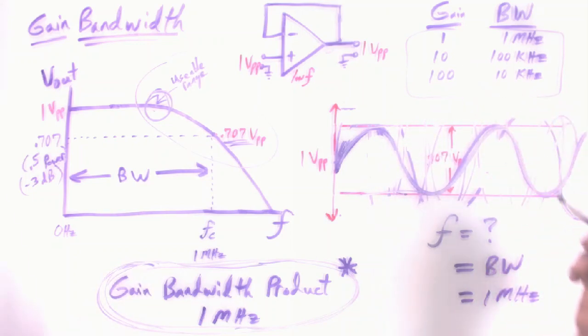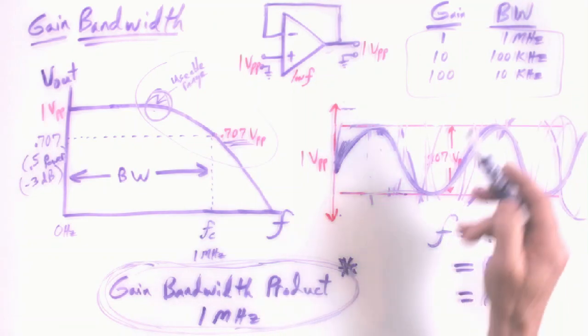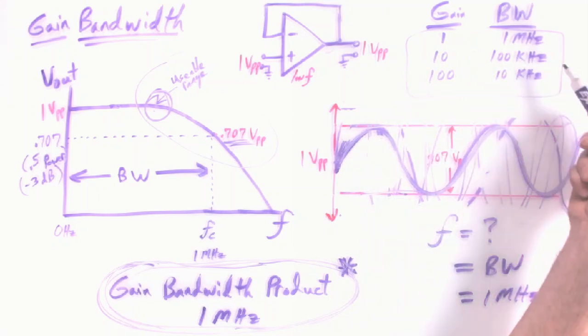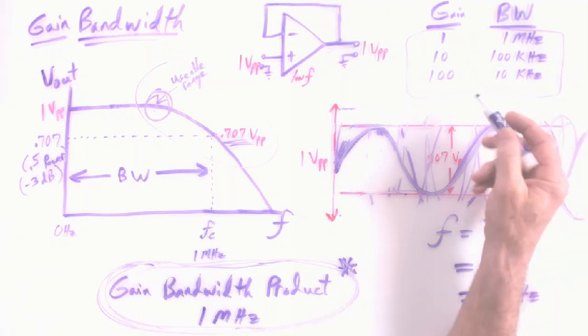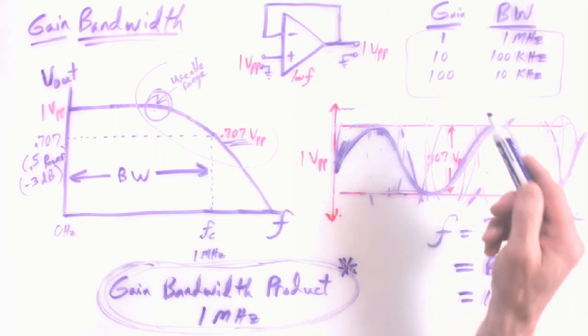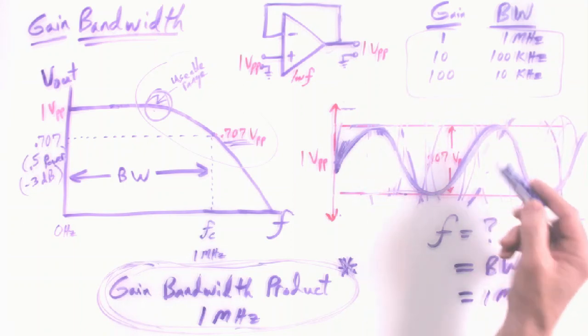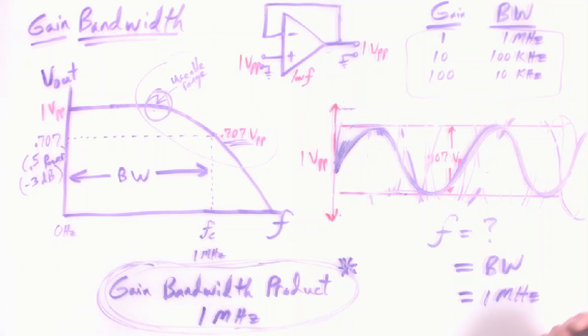and you should see. One thing I do know, whether it's going to stay perfectly constant, the gain bandwidth product, or not, you will see the trade-off. As gain goes up, bandwidth goes down. So if nothing else, we know we can hang our hat on that. That trend will absolutely present itself because, like we said before, they are trade-offs of each other. So we can at least stand firm on that. And how constant is the gain bandwidth product over the entire operating range of different gains? Not totally sure what we'll find with the 358. But again, that's the beauty of heading to the bench and experimenting.